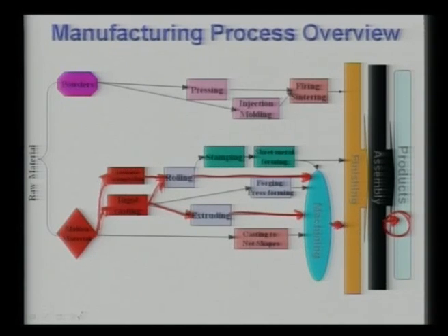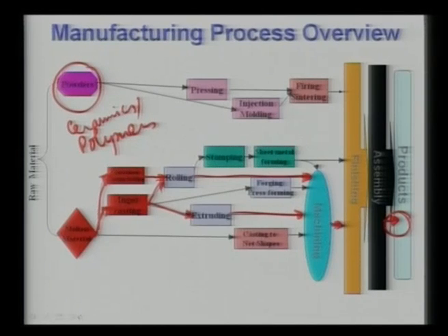The other way is powders. Powders are typically used for ceramics or polymer based materials, so these powder based manufacturing routes are essentially applicable for ceramics and polymer based materials. You start with fine powders, then press them into a particular shape, which is called a green body. This green body can subsequently be fired or sintered to make a particular product, and in this process you can get either a very simple shaped product, like a cylindrical one,